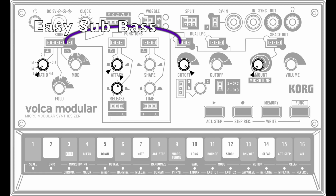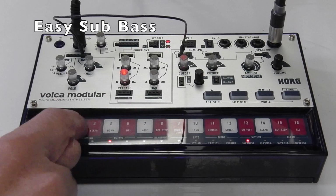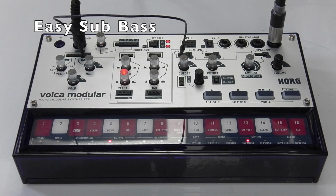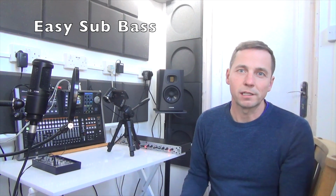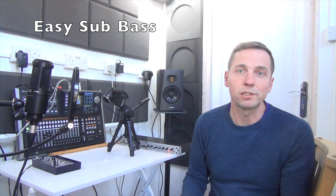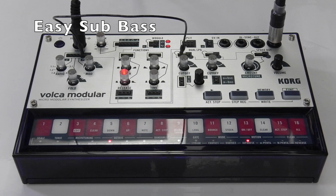This overrides the default connection from the carrier wave to the LPG1 signal input. So now we hear the modulator wave instead of the carrier wave. The modulator wave tracks the pitch of the keyboard, so it's playing the same notes as would be played by the carrier wave, but generally at a lower frequency, at least when the ratio setting is at the minimum position.